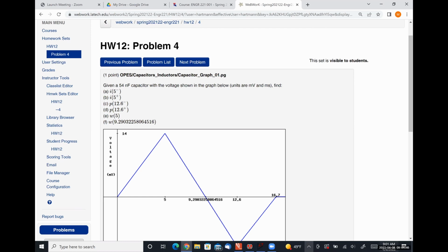In order to be successful at that, you fundamentally need to understand at a minimum the voltage and current relationships for capacitors and inductors, particularly paying attention to the fact that the voltage drop across a capacitor cannot change abruptly and the current flowing through an inductor cannot change abruptly. Everything that we're going to do for literally the next week and change is really based around those two observations of those derivative based relationships. All right, that's enough out of me for today.